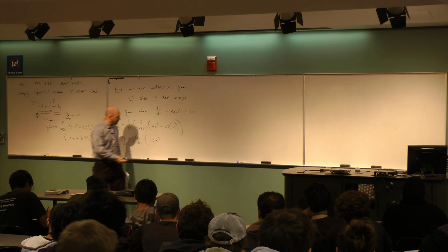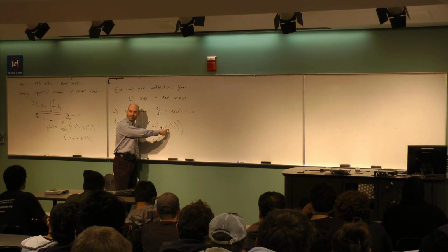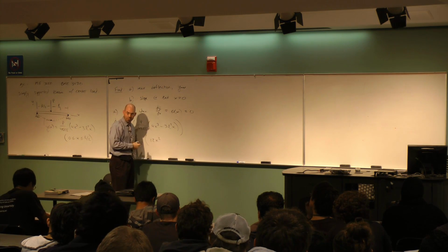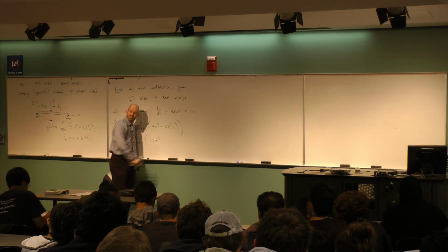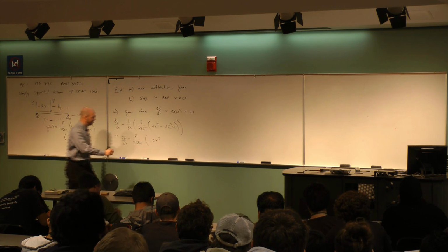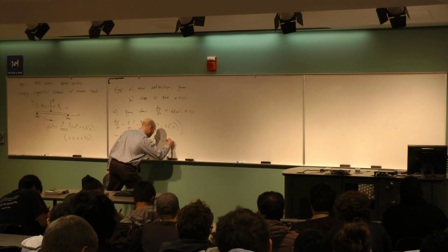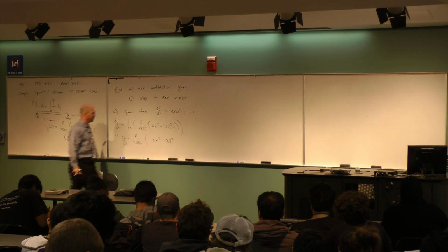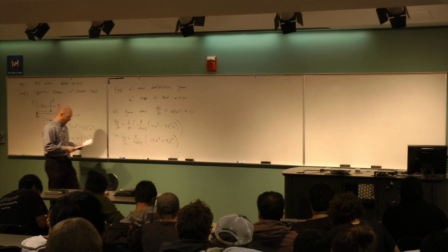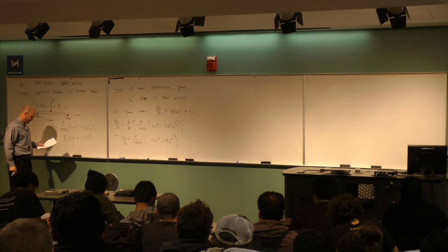Frequent mistake students will make, they'll take the derivative of this L, and they'll say it's 2L. No. L is the length of the beam. It's a parameter. We're taking the derivative with respect to x. So the L in this case is a constant, right? So it's minus 3L squared for the constant. Derivative of x with respect to x is just 1. Okay, so that's it. All right, so I get that guy right there.